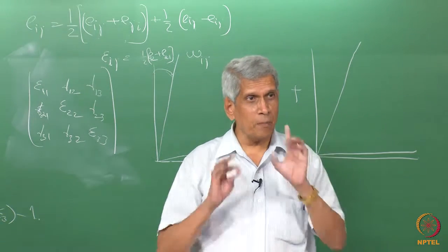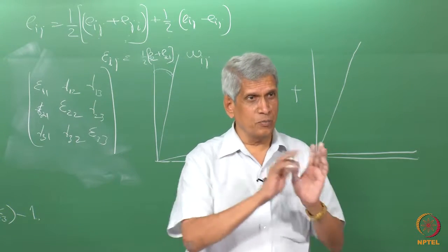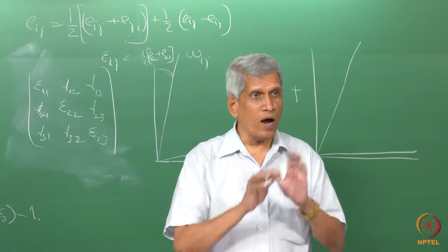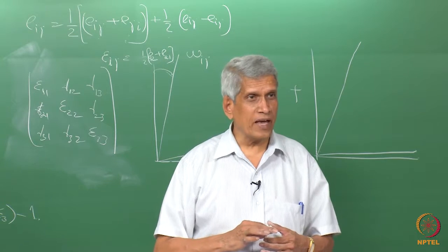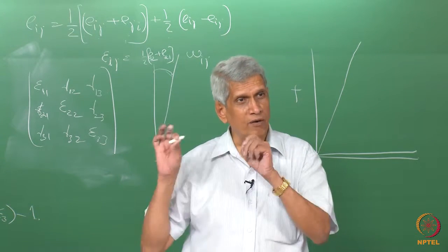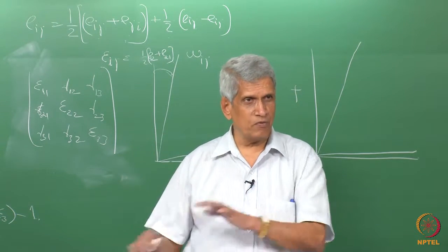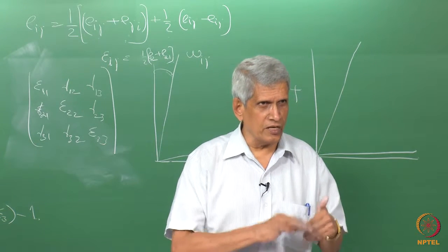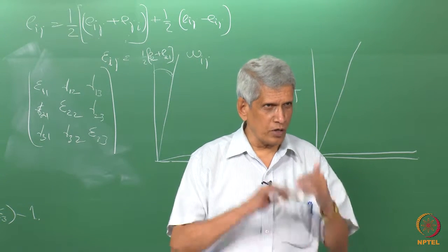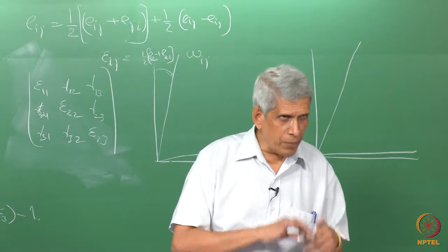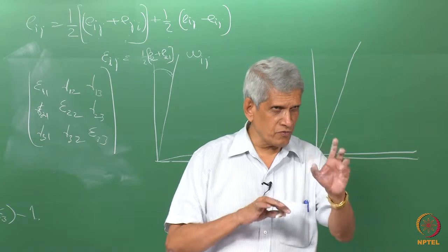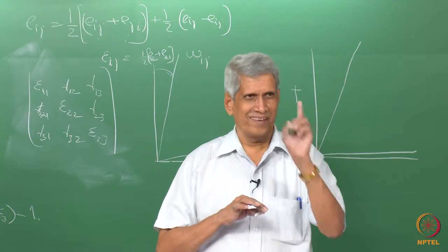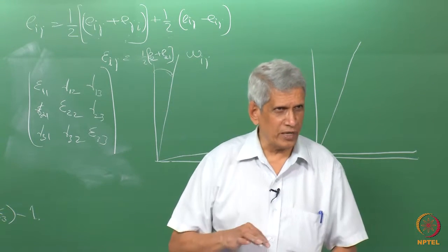Rotation part is, the sample is undergoing only a rotation. It is being sheared and rotated. So what we do measure in these ones is only the displacement. From that we are calculating it. So the displacement always inherently has, from displacement if you try to look at the strain, shear strain, that has a rotation part plus an actual shear part. That is the one which one has to be always careful about.